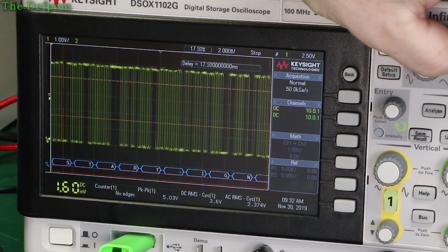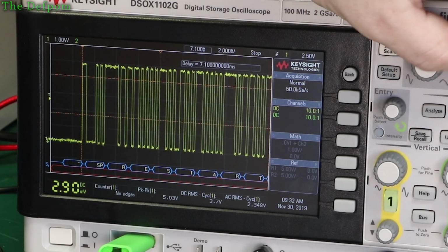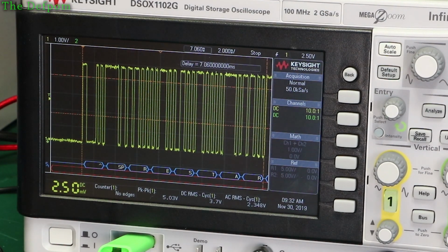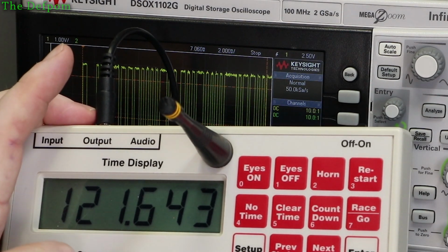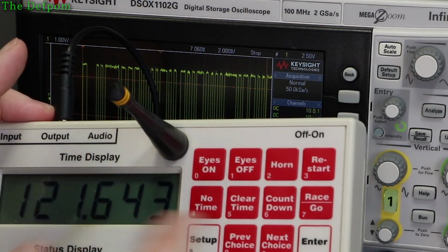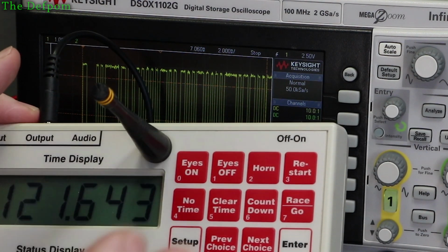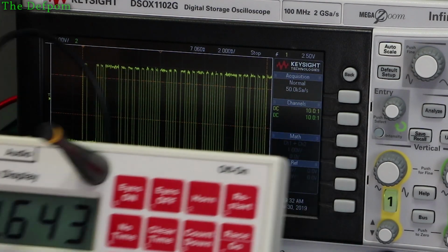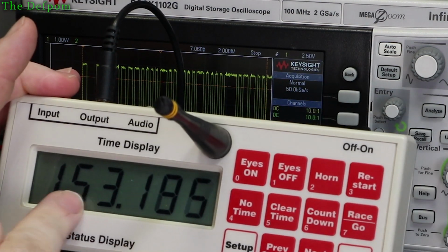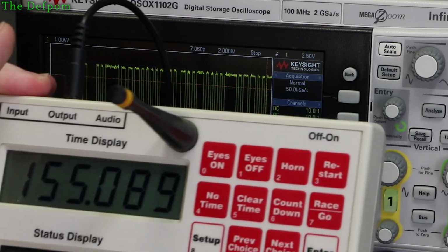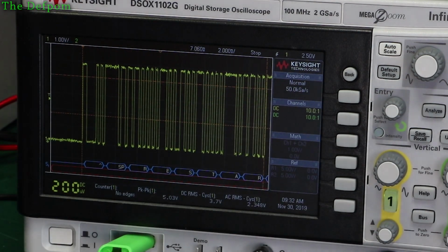So what can happen is this has the ability to detect if there's a fault, and you can push a restart button. Like so, the time will stop. So if the time stopped, but you realise, oh no, it's been falsely triggered by, say, a fly flying through the light curtains, for example, you can push the restart button and it restarts the timer. Alright, so I'll do it on here. There it starts, carries on from where it left off. Okay, so it's still counting in the background.